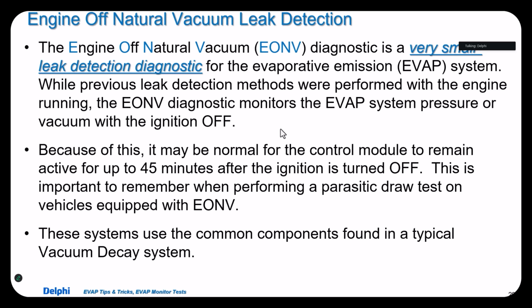That can be anywhere from, I've seen 5 minutes to as long as 45 minutes. And if the pressure isn't high enough, it could take much longer to cool into a vacuum. GM used to say it could take 7 days to do the key-off system. Chrysler used to say it'd take 1,080 minutes for the system to completely test. You're not going to sit around waiting for that. You're going to shut the car off and hope that it works. But that's just to give you an idea what it can take.